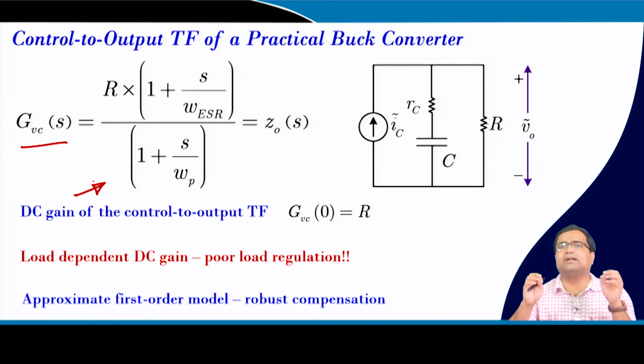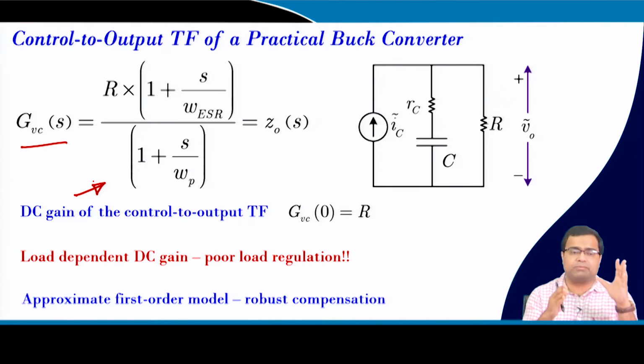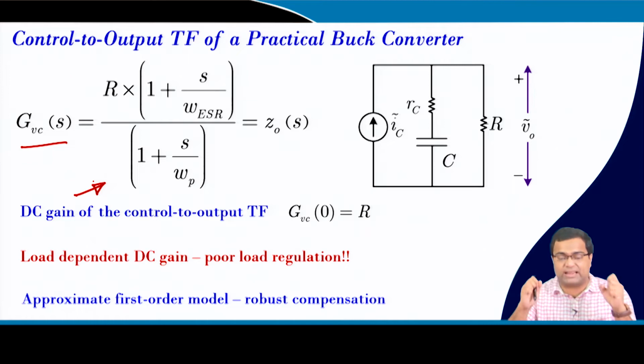It was even very difficult to compensate. Even exact pole zero cancellation was not sufficient when we were operating under light load or higher load resistance value. In the actual circuit we saw oscillatory behavior where our model response was perfectly fine, because that was due to the poor damping in the actual switching converter. But since we have closed the current loop, it virtually looks like a first order system, so the compensation becomes much more robust. There is no double pole effect, neither is there any Q peaking.